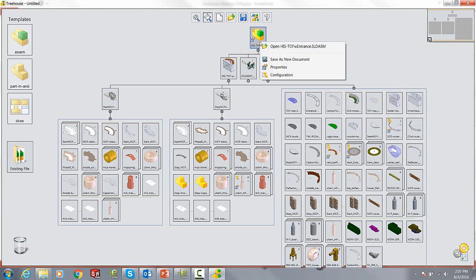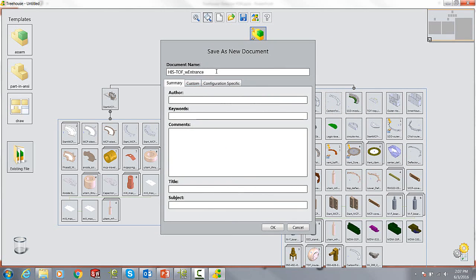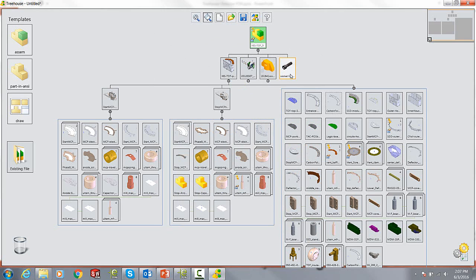Now the next step at this point is to generate a new version of this. So we're going to give it a new one, version 9 in my case, and yes, there are 8 previous versions. And notice the icon goes green. So if I save this structure out, it's going to be a new assembly structure, and I can export that new structure all the way out to SolidWorks and have it reopen it with new items. I can also drag and drop new parts using templates of my own and start building up new components.